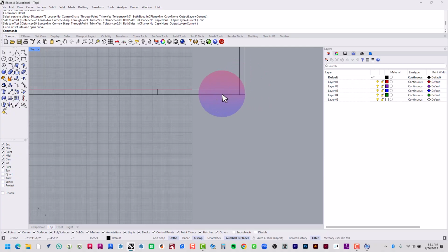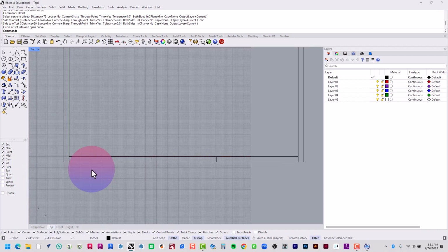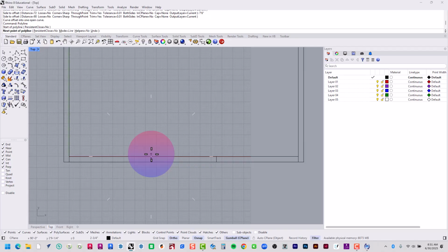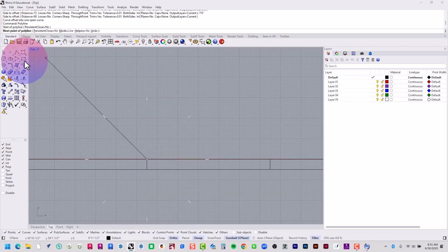And then to draw the doors, I'm going to type in the polyline command. And I'm going to start right here. Actually, let's do the rectangle command. I'm going to hit escape. I like to use the 3-point rectangle when I make my rectangles, and I want to represent the doors. So I'm going to start right here.